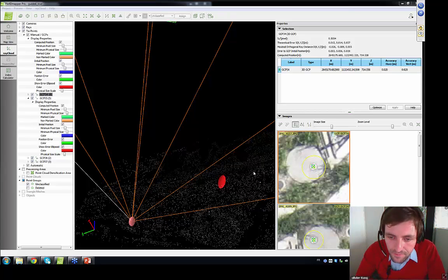All right, another question. What is better: a few manual tie points clicked on many images, or dozens of manual tie points clicked on few images? Oh, okay, that goes back to this question. The goal is normally, if the project is good, meaning it has enough overlap, that you really don't have to add any manual tie points.